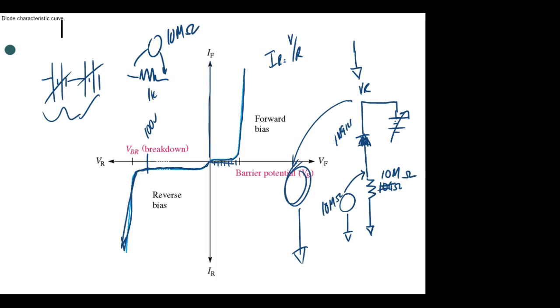Now, I'll tell you the story about Dennis Ramsey shutting down number 4 gallon line at US Steel. He was trying to measure the output of a mag amp. The mag amp is a high resistance device, and he put his meter in parallel with it, which changed the output of the mag amp. The mag amp thought the line had an overcurrent condition and shut the whole line down.